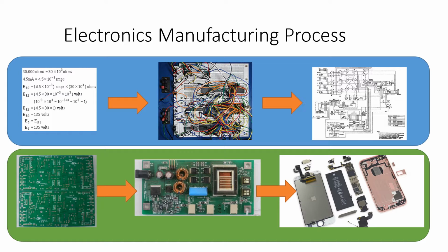And there's a whole bunch of things you have to know about the electrical circuit and the schematic before you do that. You have to know which parts get hot, where they're located, so you don't have parts that burn out. You have to make sure that parts that need electromagnetic interference shielding aren't near each other, because you'll have interference between them. You need to design for manufacturability, so the circuit board is a standard kind of size and follows standard hole dimensions. You need to know where to put thermal vias to remove some thermal heat.